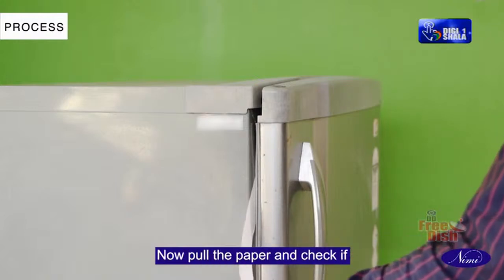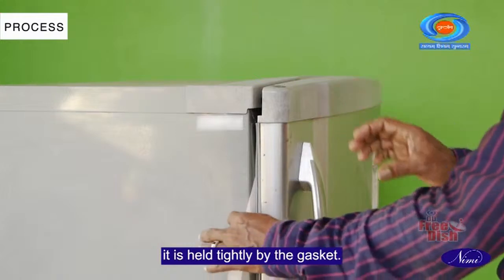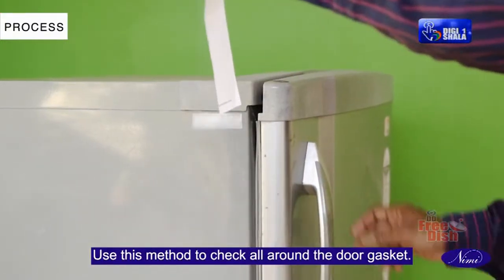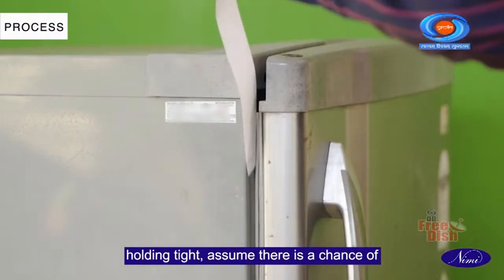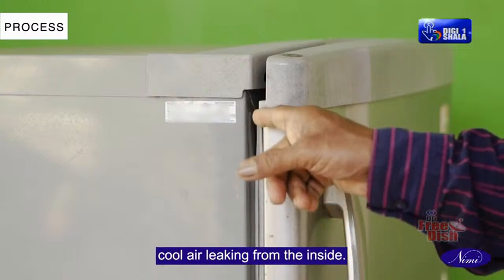Now, pull the paper and check if it is held tightly by the gasket. Use this method to check all around the door gasket. If, in certain places, the gasket is not holding tight, assume there is a chance of cool air leaking from the inside.